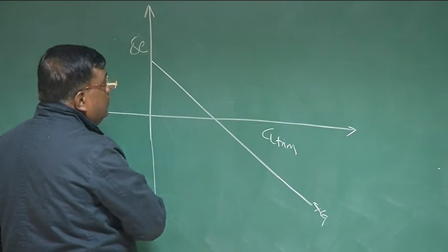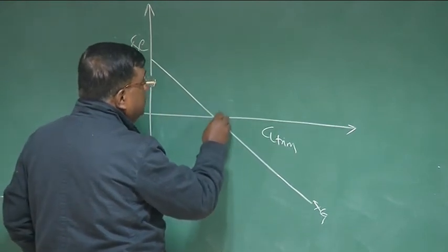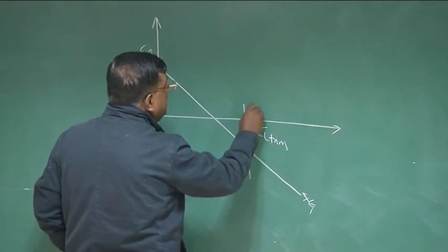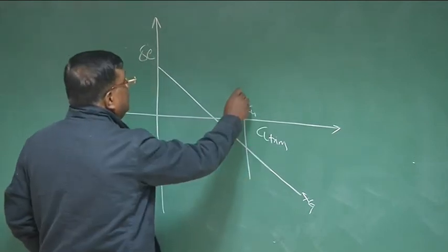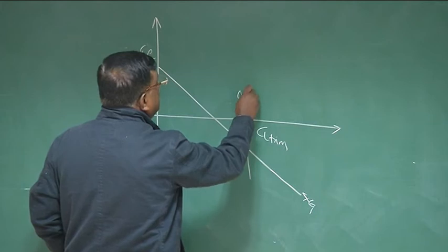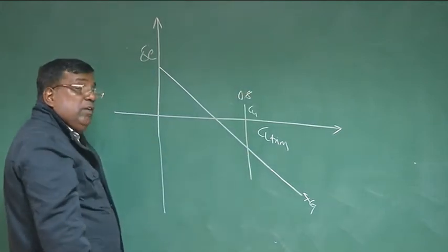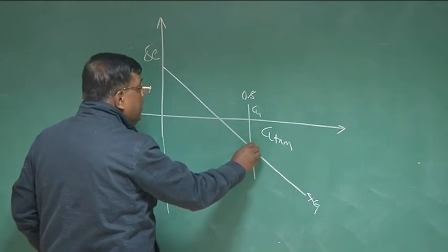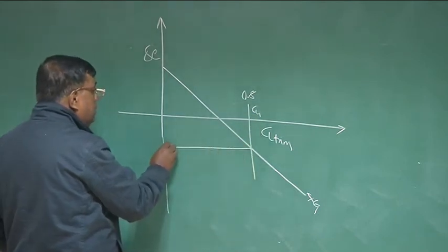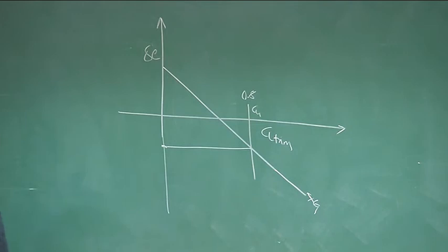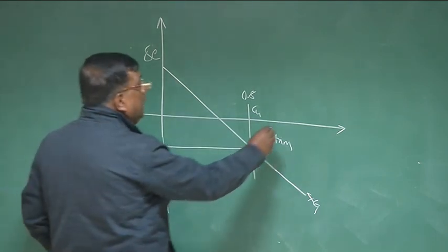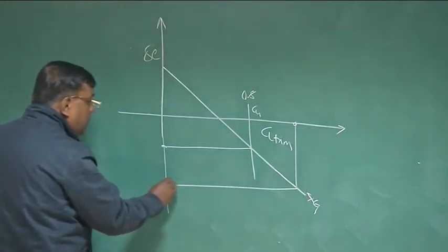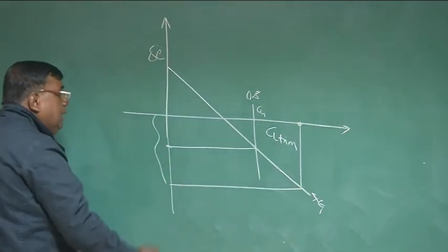Let us see here. Suppose I ask a question: can I trim the airplane at this Cl1 or not? Let's say this value is maybe 0.8. Immediately what will we check? For trimming the airplane at 0.8, how much elevator is required is given by this value. Now somebody asks, can I trim it here? And you draw here. Then this is the delta E value required.